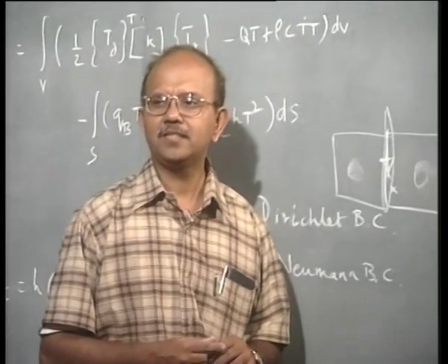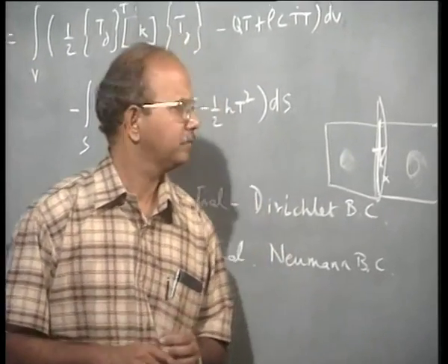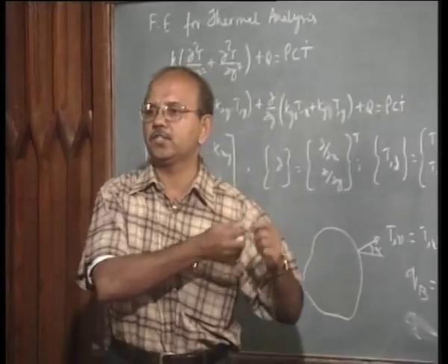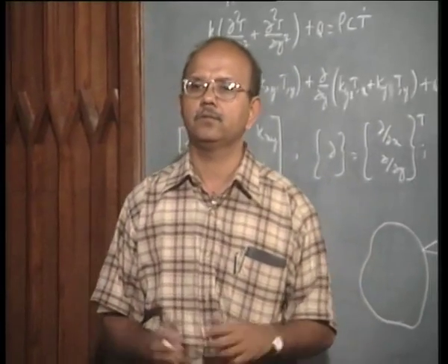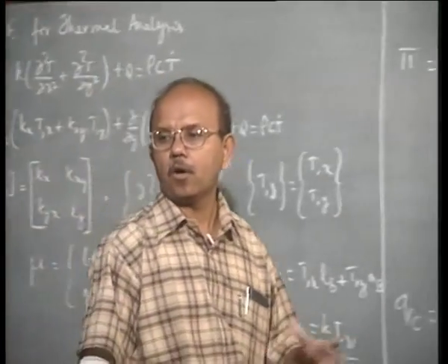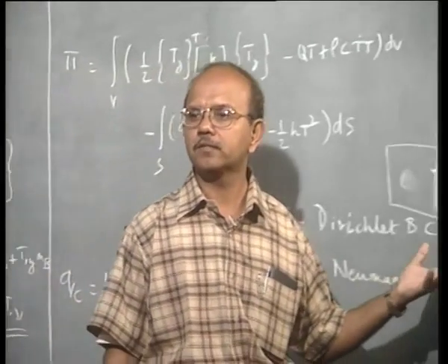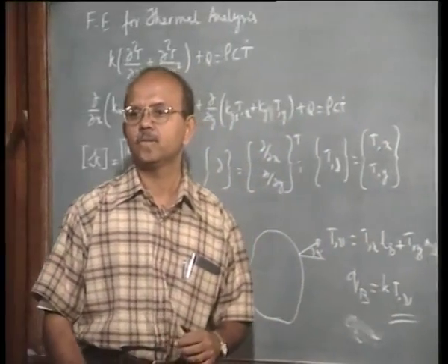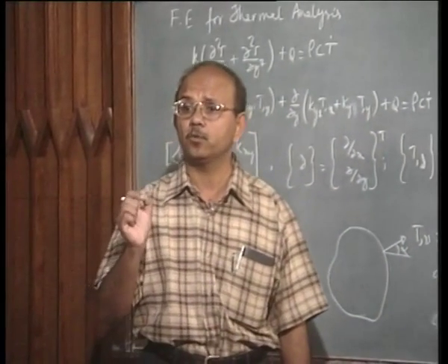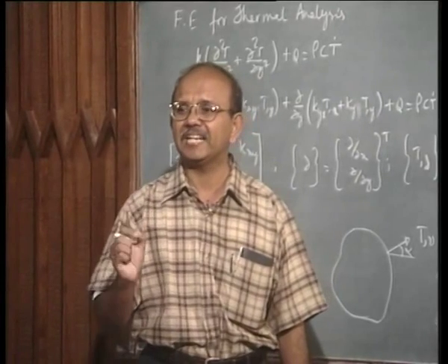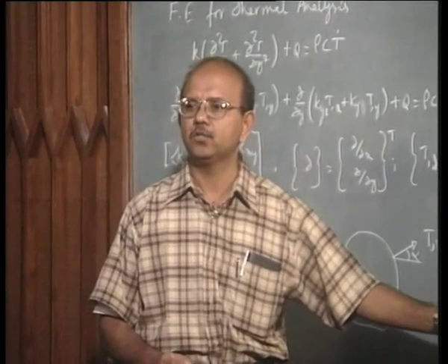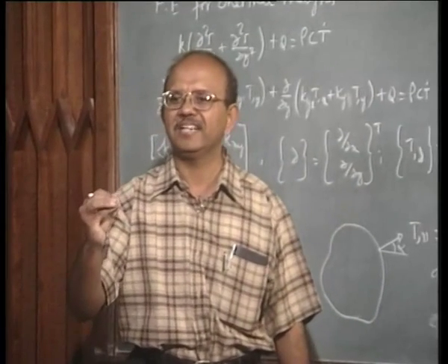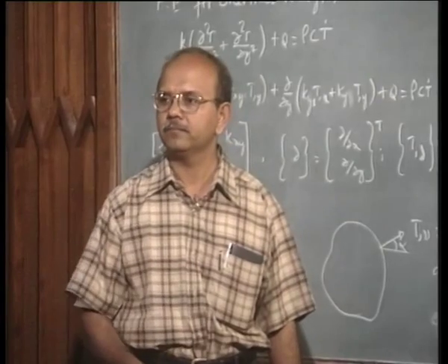Now, let us go ahead a bit to understand this problem. How am I going to give this heat flux, the torch that is going to move due to arc welding? So, for example, how am I going to give this heat flux? This is the Q input. This can be directly given. I need not go to K and so on. The heat input due to arc can directly be given as QB.